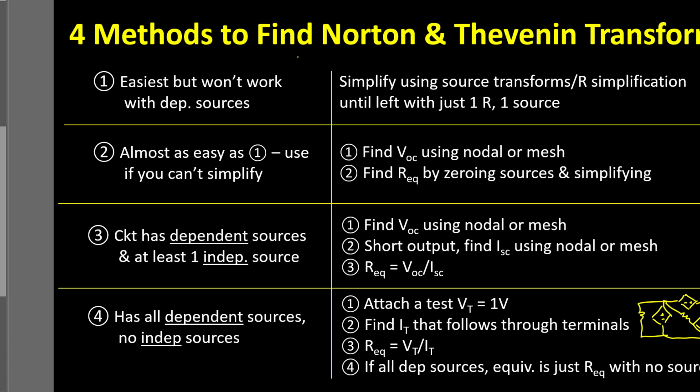Determine what current flows into the terminals. And then your single resistor that models everything to the left of those terminals is just V test over I test.